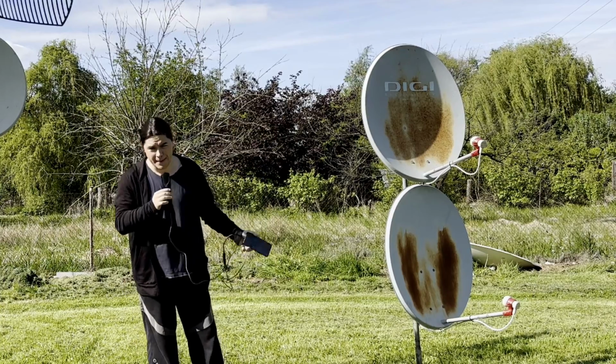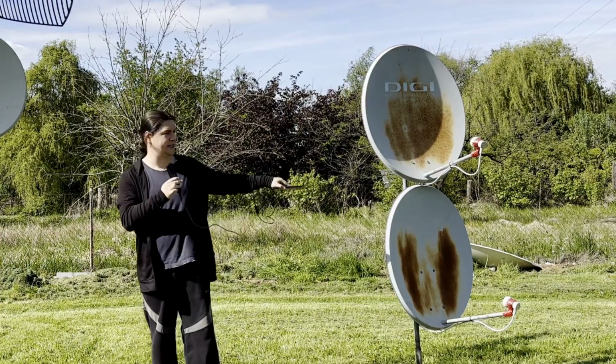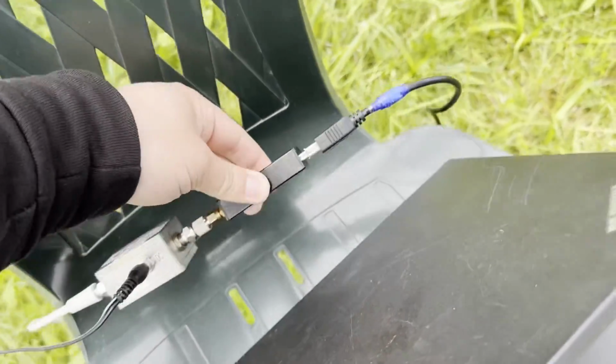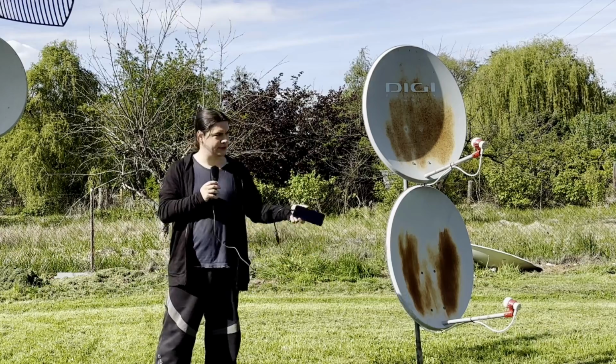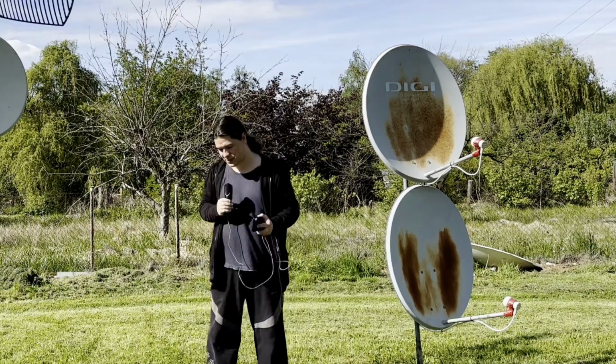That's a quick way to damage it, so it's always worth making sure you have everything connected properly before powering it up. After the bias T is where you would put your attenuator. You do not want to put the attenuator between the bias T and the LNB. After that we have the SDR itself, and between them you would need an F connector to SMA adapter, again relatively cheap to get. And finally we get to the SDR itself.